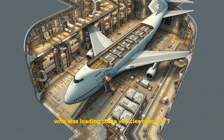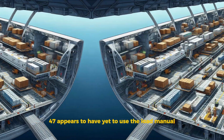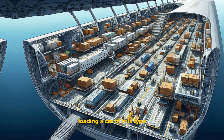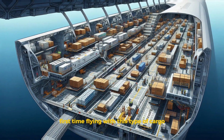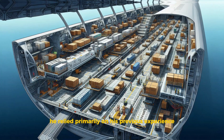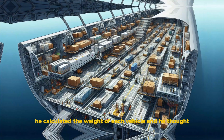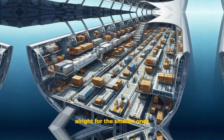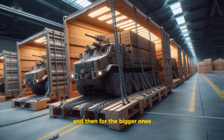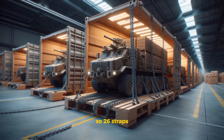The loadmaster who was loading these vehicles onto the 747 appears to have yet to use the load manual, even though this was his first time loading a cargo of this type and the flight crew's first time flying with this type of cargo. At that point, he relied primarily on his previous experience. He calculated the weight of each vehicle, and he thought, all right, for the smaller ones, we're going to need 24 straps to keep it in place. And then for the bigger ones, we would probably take 2 more, so 26 straps.